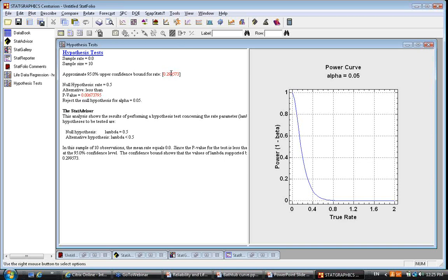I don't think there's much more I can say without at least one failure, which is why we started with, for example, some accelerated life testing, with my example of the Arrhenius plot early on. I had to make things fail so I could extrapolate back to normal conditions to get a reasonable estimate of something like the P50 value. You all are making me think on my feet today.